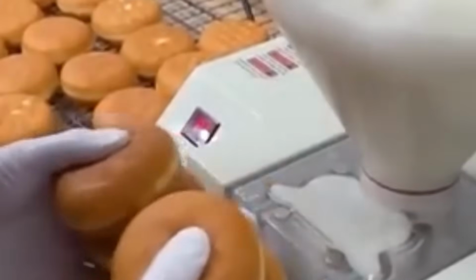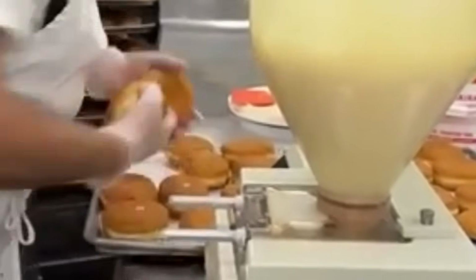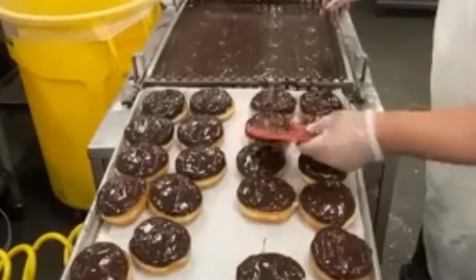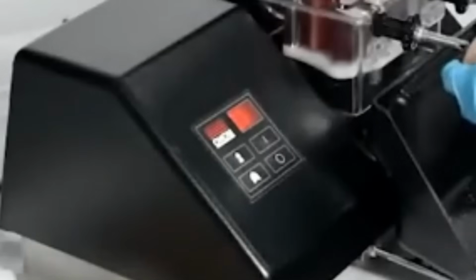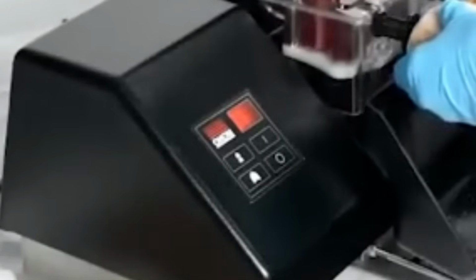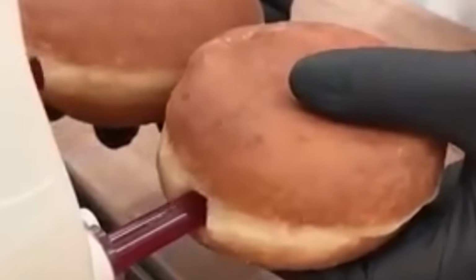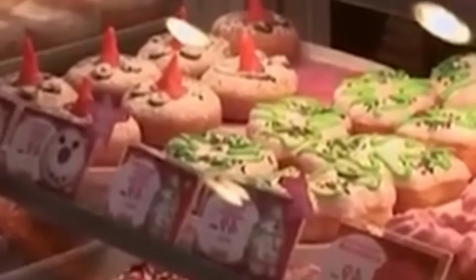The fryer is filled with vegetable oil, maintained at 190 degrees Celsius using immersion heating elements. The belt submerges each donut halfway and flips it midway to ensure even browning. Frying time is approximately 90 seconds per side. Excess oil is removed at the fryer exit using an inclined drip section. A vibrating shaker assists in shedding residual surface oil.